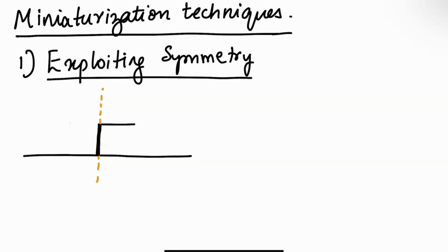Okay, and then I can draw this a little bit to make it a bit thinner. So that's my shorting pin, and I have only patch on one side now. Of course, I still have my feed, which was coming in close to this end, right? And this is my coax.